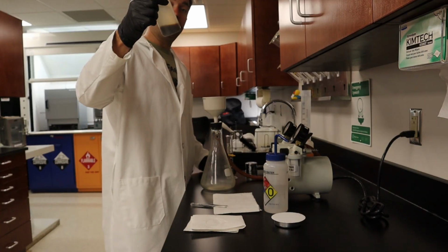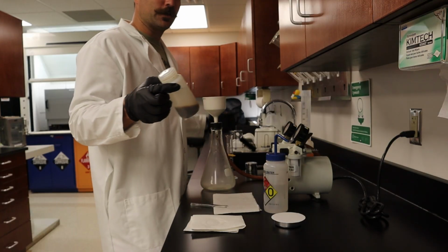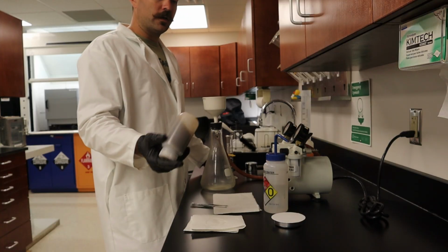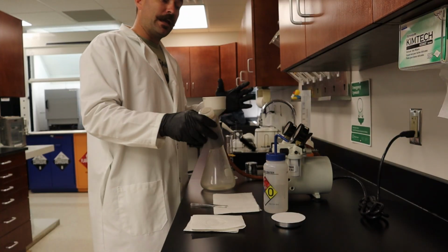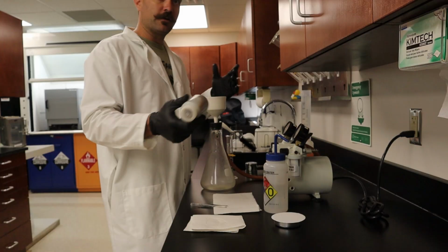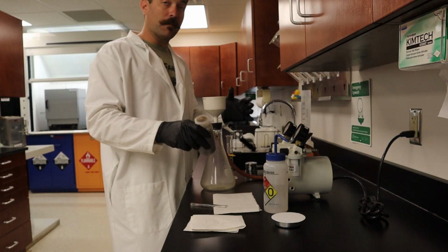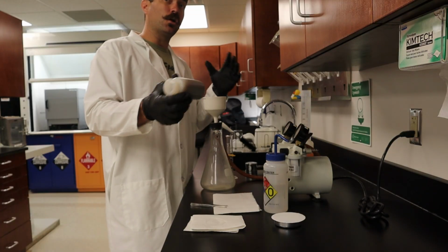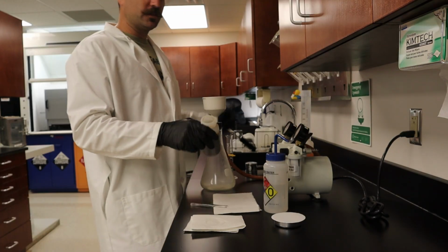And that would be a very big misrepresentation of our mixed liquor if we did not actually shake this back up. So we're going to gently mix this back up. And you don't want to worry so much about floc shear in this instance. We are actually going to be measuring the weight of the sample. So the better it is mixed and the closer it is to how it was when you sampled it is